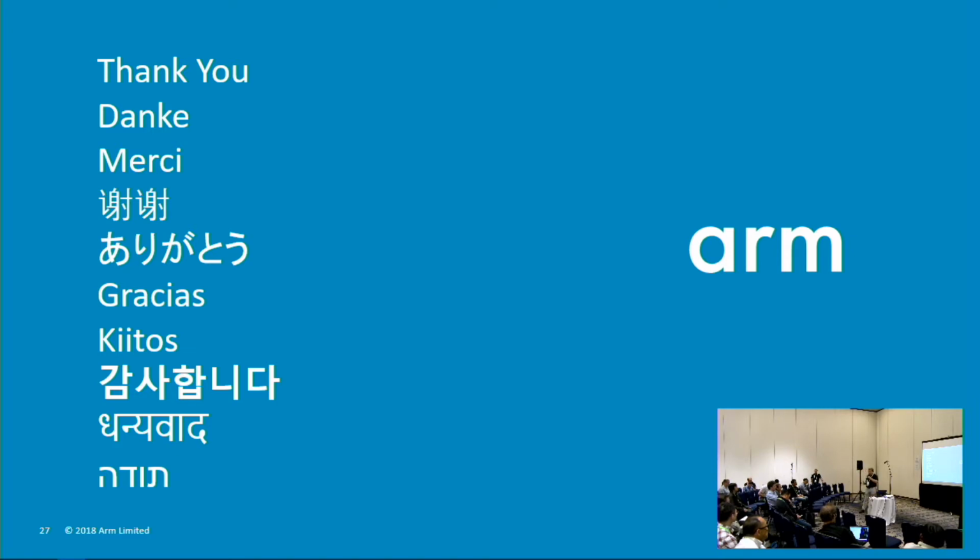It is a difficulty, and we would like to get at least some scripting tools to explore, see if we can see the system available in SysFS and try and run it up, see if we can get some trace out of it. But it is all very dependent on the platform landing team having set up the information in the device tree in the first place. So if the device tree is right, we can generally prove that there's a system working, but we can't say your device tree is wrong. It just doesn't quite work like that.